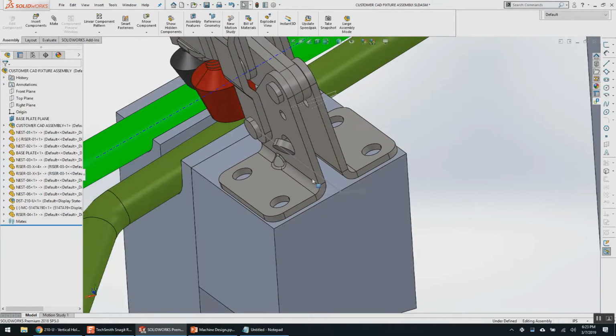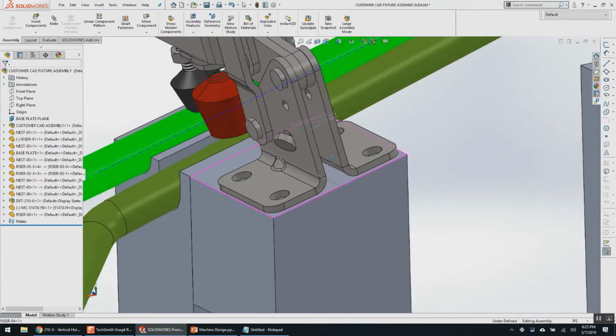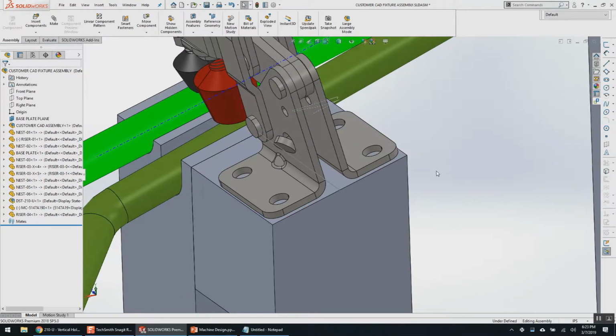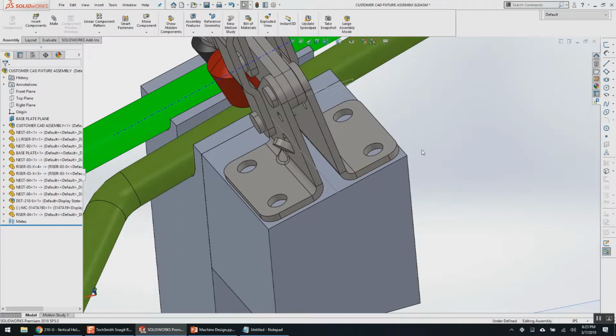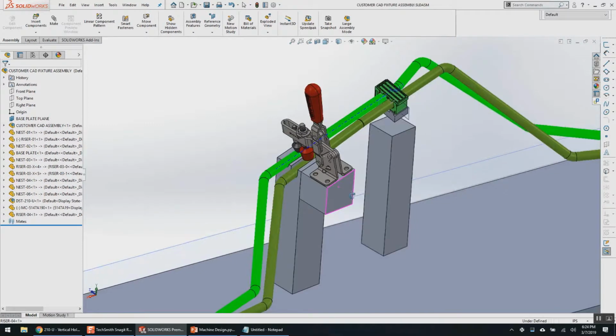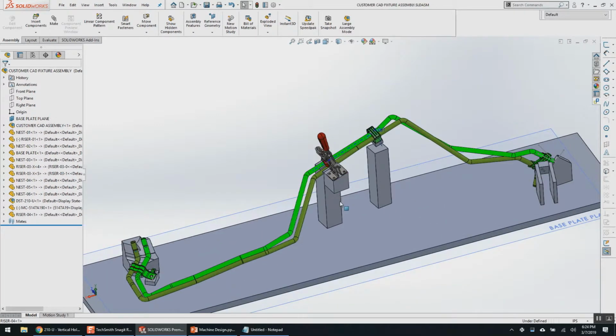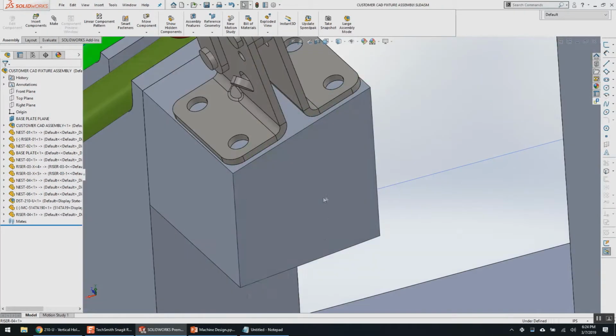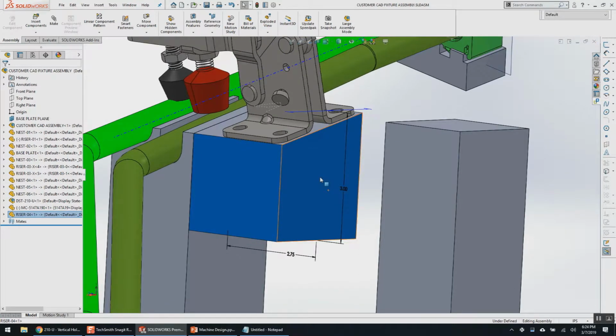So I'm going to pick that. Again, breadcrumbs are awesome, guys. If you're not using them, use breadcrumbs. It saves you so much. The standard SolidWorks key for that is D, as in Delta, but the breadcrumbs are fantastic. So then I hide the line because all good designers hide extra lines, axes, and planes if they're not being used actively or unnecessary to see. And I'll get rid of the rest of this at some point. That's my opinion, at least.